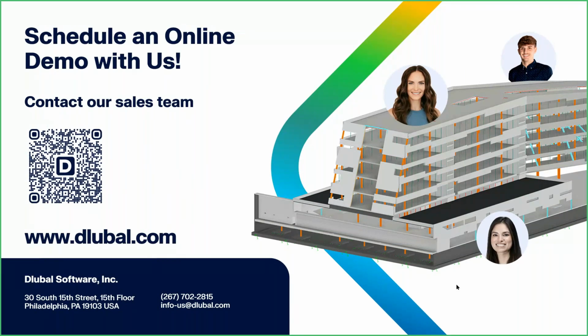So if there is a situation where possibly a drafter is on one computer and an engineer is on a different computer, we're not going to have these direct integration capabilities. As far as we know, there's no export of the analytical model from Revit, so therefore we would export the physical model as an IFC. So this is what Alex had showed with the import into RFEM. Unfortunately, the downside of IFC is, of course, our physical model: things are not fully connected. So therefore, we showed how to connect those elements with those rigid links.